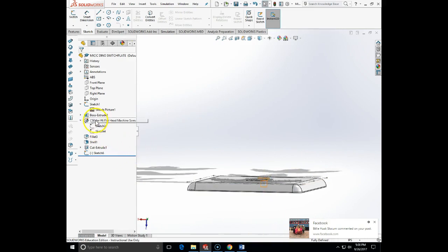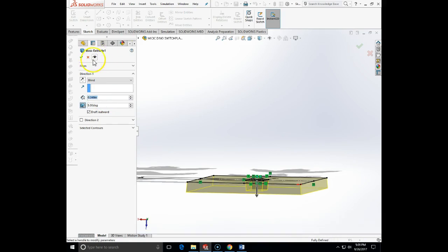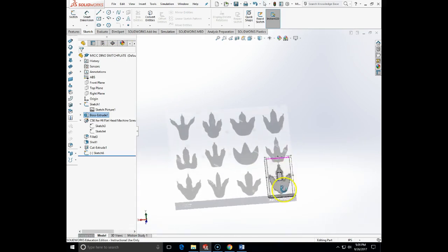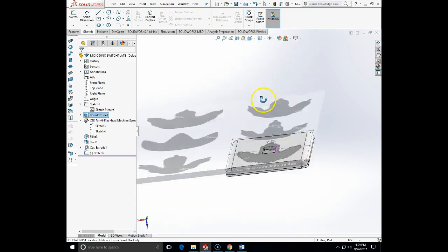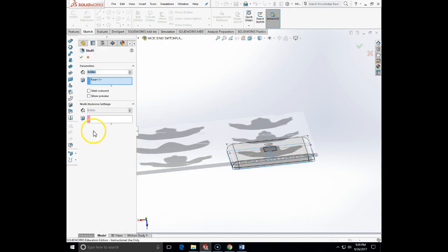Another modification that I'm going to make is I'm going to do the cut for the 50 thousandths. I'm going to put 0.259 for the extrusion. So I will make it just slightly thicker so that there is actually a place to cut. And the shell, when I shell it out, I'm going to make 0.09 plus 0.05.